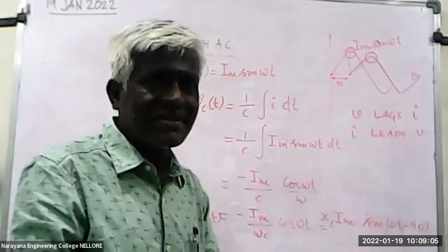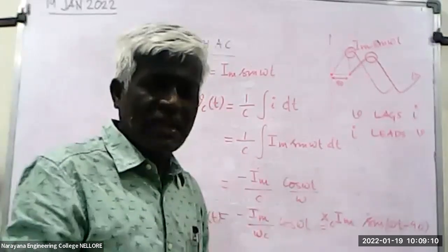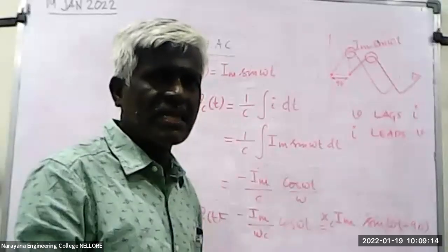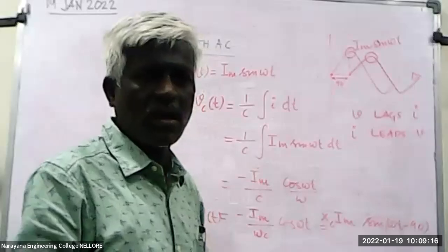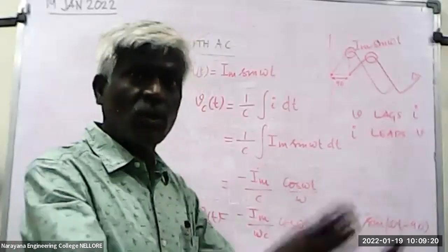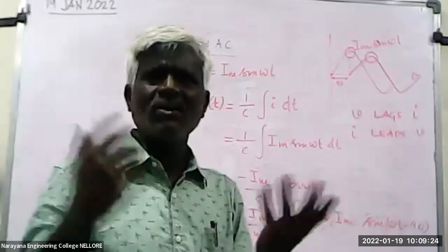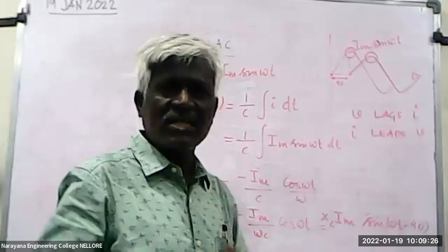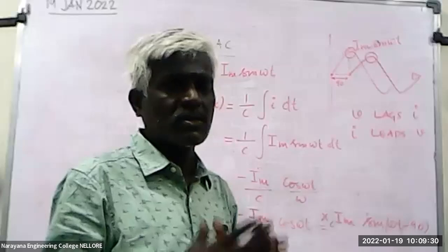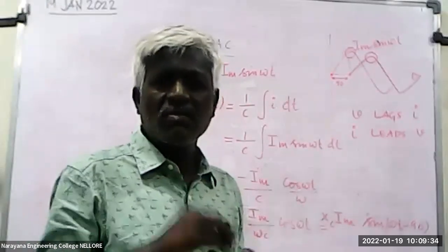Almost all loads are inductive. Mostly no loads are capacitive. Very rarely are loads capacitive in nature. They may be resistive, like heating loads. All heating loads may be resistive loads. All other motor loads and pumps are there. They are the major loads. Lighting loads are very small loads, right? In industries, there may be huge pumps, 10 HP pumps, 20 HP pumps. So they are very huge loads. When you consider them, these capacitive loads are very small.